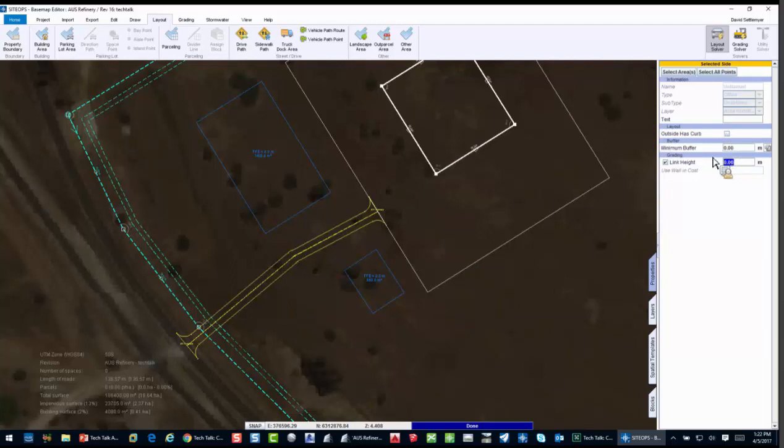I need this to go down and dig a hole. I'm going to tell it, let's go down to -3 meters. And immediately it's going to pop up, use wall as cost. We could do that. We could leave it off. Let's say for this one, I'm going to take the wall cost off because it'd be part of probably a different cost item building this.